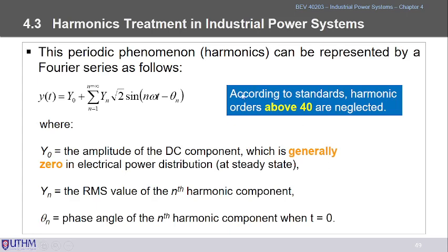Of course, in harmonics we are dealing with frequency. Frequency is our main concern, and we have to analyze the waveform that we capture from the power quality analyzer using the Fourier series. The Fourier series will look like this. This is very basic fundamentals. Y is the total resulting waveform, and the capital Y naught here is the DC component.